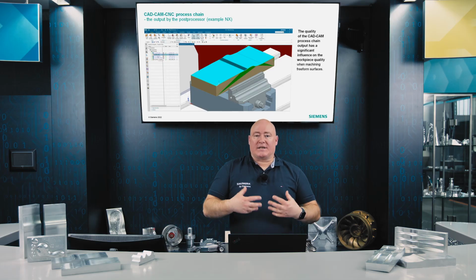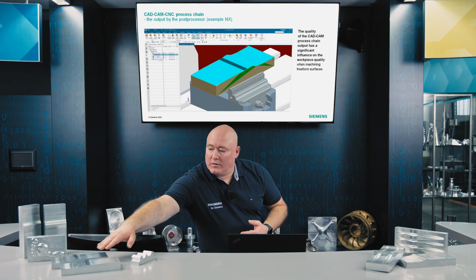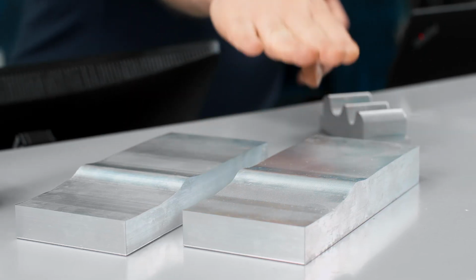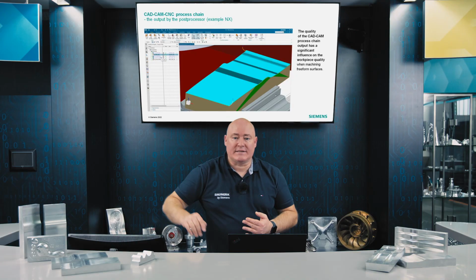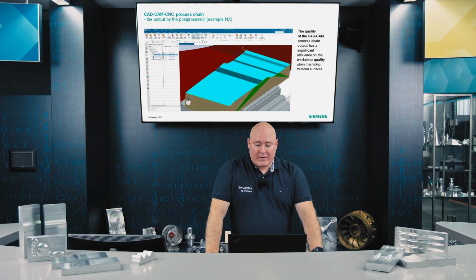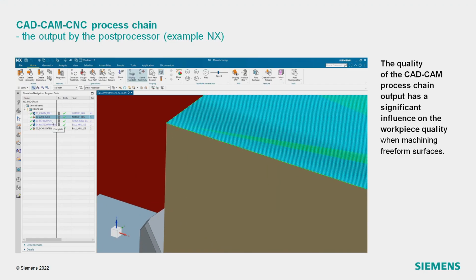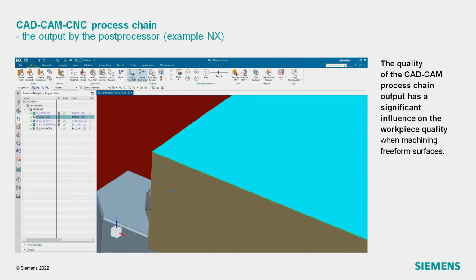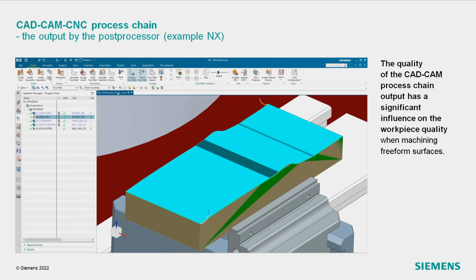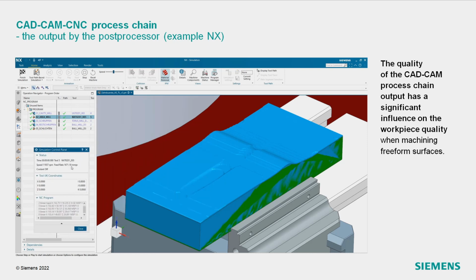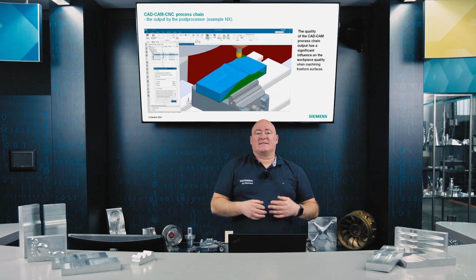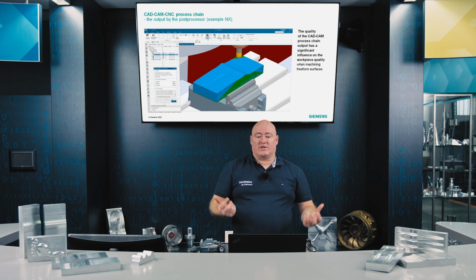Let's mill the separation plane. This is the area where the 2 injection molds, the top and the bottom, come together and also come apart again, where they separate. As I already mentioned, this separation plane is then roughed and finished. Here you can see a 3D surface milling operation, which is now to be converted into this NC program. After clicking on this operation and moving it to the surface, we can compare the programming with the simulation to check that the whole process will actually be collision-free and reliable and function as intended.